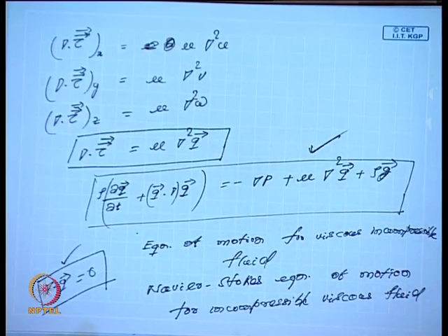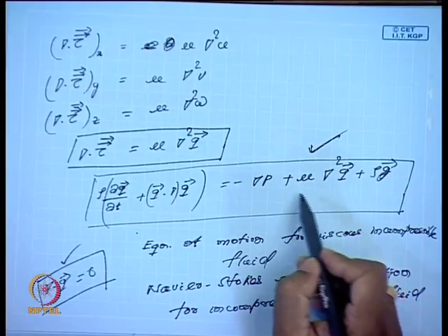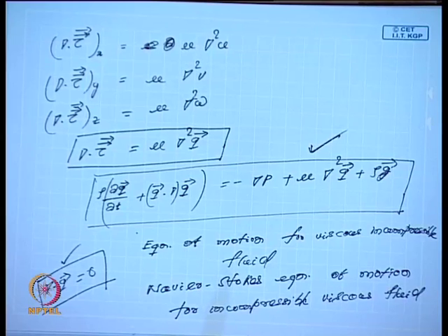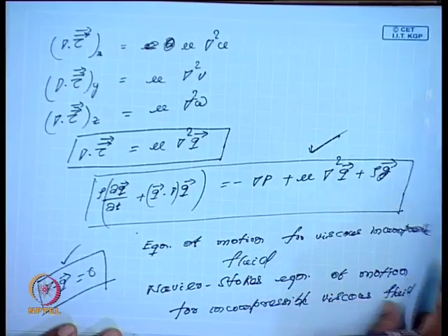equation. In fact, the approach we have seen in the derivation of the Euler equation, that is the rate of change of linear momentum is the total force. The same Eulerian approach can be used, only thing is that when we calculate the total force, there is another additional term, the viscous term, which comes into the picture, and this viscous term is based on the assumption of Stokes, basically based on Stokes postulate. It is one of the simple derivations.